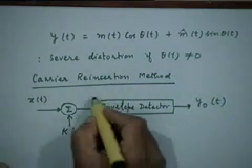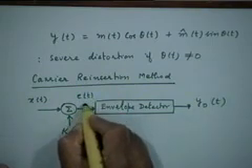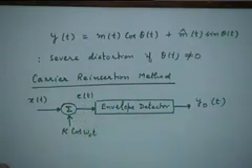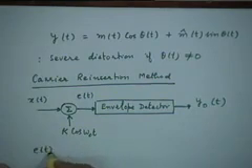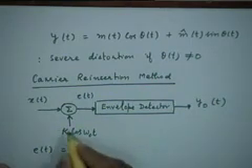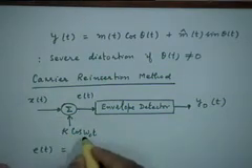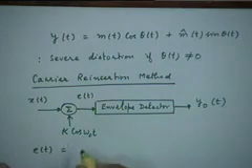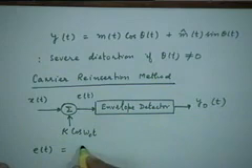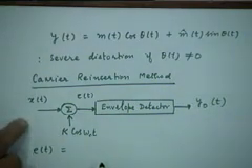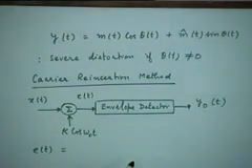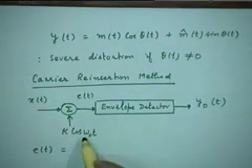To see what happens, let us consider the signal e(t) at the output of this adder. What does it look like? It contains the SSB signal coming in plus the local carrier, right? So if you remember, x(t) is m(t) cosine omega ct plus m hat(t) sin omega ct, and you also have k cosine omega ct added to that.